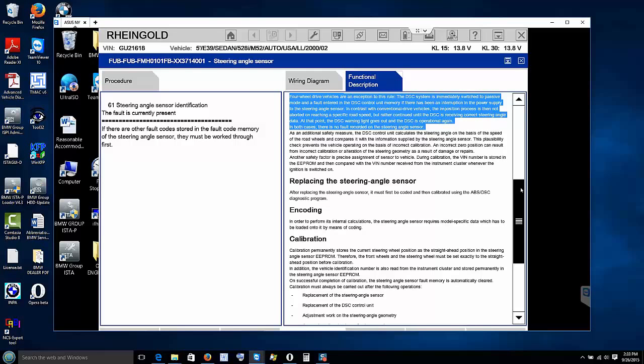So if somebody repaired it, damaged it, or something was done on the car which caused it to have an incorrect zero. You remember when we put the steering wheel at zero? Yeah, that is the zero position this is talking about, because there's no angle or geometry recorded in terms of negative or positive number until you turn the steering angle. You know what I mean? So basically, the zero position is when the wheel is not turned at an angle.